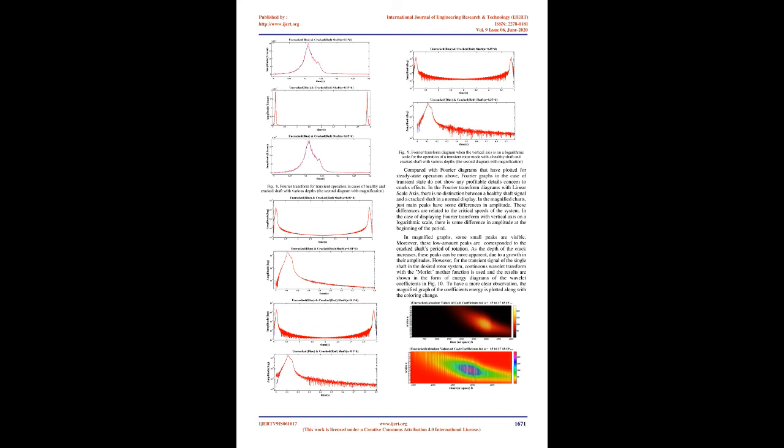B. Transient analysis. The responses of a rotor-bearing system are unsteady state or transient when it starts from the stop mode, it has an incremental acceleration, as well as when it is turning off, it has a decreasing acceleration. Therefore, to analyze the transient operation, the starting up situation is considered. In this case, the time signal, Fourier transform, two modes, and continuous wavelet transform coefficients are compared. It should be noticed that the system is going through its first critical speed.